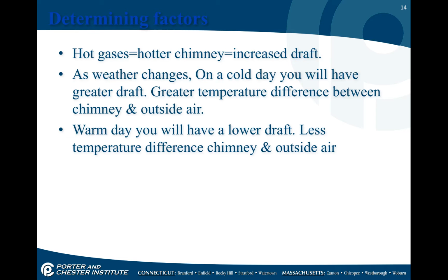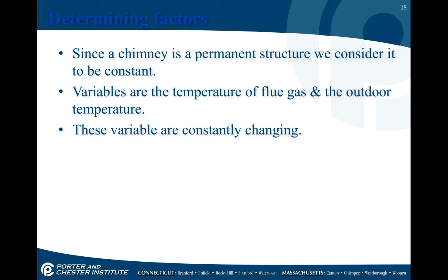So the less temperature difference between the chimney and the outside air, the lower the draft. So again, as the temperature difference increases between your inside and outside environment, or the inside flue temperature and the outside air, the better your draft is going to be.